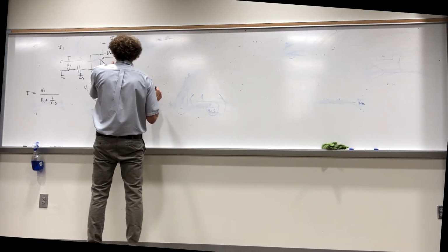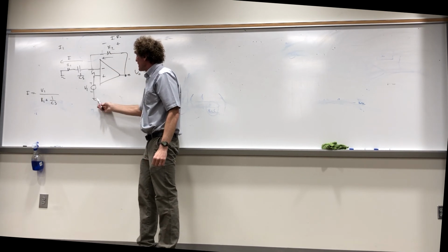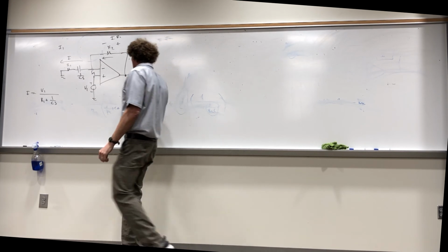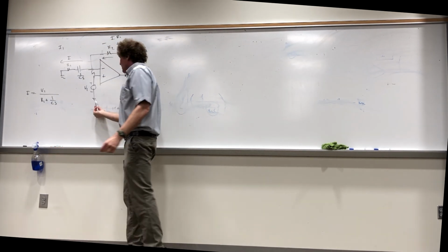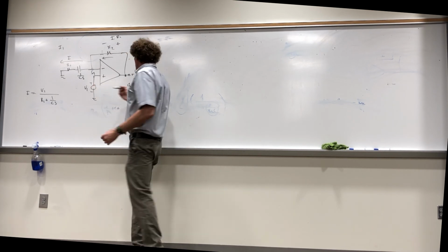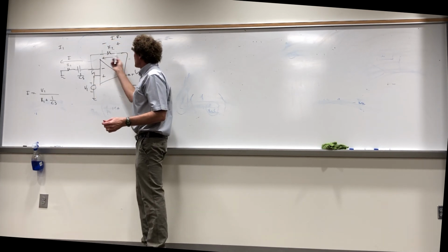Now, if you have that, what is Vout? You'll notice that's plus to minus. If I start here, I go up V1, right? Work with me. I start at the negative terminal. I'll even draw it now. I start at the negative terminal, start here, right? That's 0. Increase of V1. Do you agree? So right off the bat, I get V1. Now what else? From here to here, it's what?